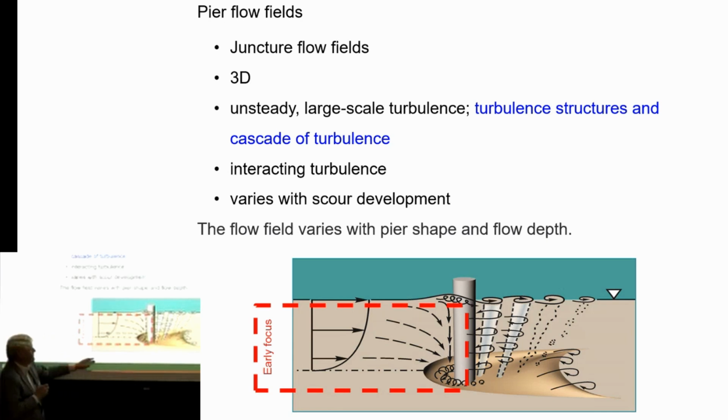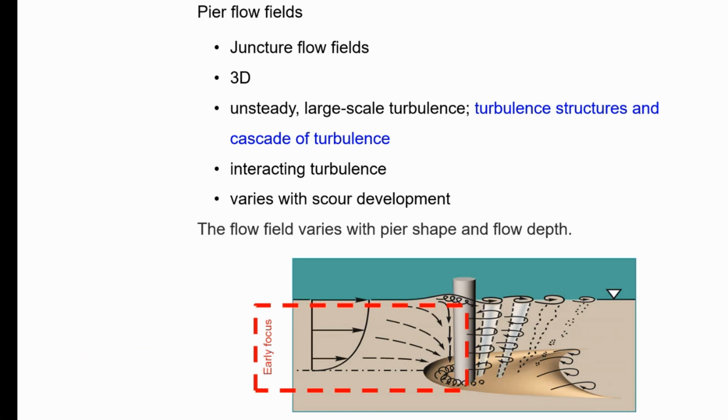Also, we have erosion here, downflow here. We have a bow wave here, the horseshoe vortex, which generates other vortices, separation vortices. We have a depositional zone here, which tends to flatten out with time, an interaction of these turbulent structures, which are very complicated. As we talked about with contraction scour yesterday, and Yong Lai knows this very well, this is quite a challenge to model numerically. Certainly, it's the simplest model to do physically, but without understanding the flow field.